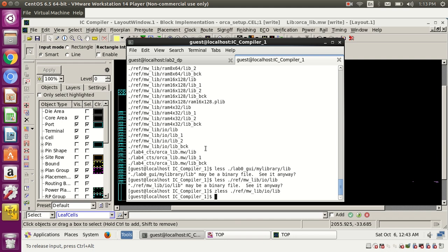What happened is, in a full design, all designs may not use clock gating, one or two designs might not use it, but some CAD guy who has written this flow might have put clock gating on for you also. The tool will work in some other way, it may externally add some clock gating cells. So you should just know that there is a clock gating cell. In this path this cell should not be present, but it is present, so that means there is a clock gating path. So you can ask the designer, or you can mail your lead, this cell is giving high delay, or this cell is giving unrealistic values, from this cell the clock period is changing. You can say that.